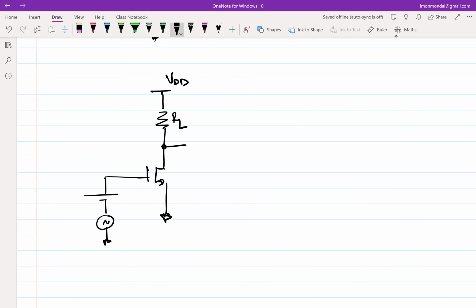And then we saw that if you have RL here, there is only so much gain you can get for a particular voltage supply. Then we said that we will not use RL. We will use a current source, and then try to bias it using negative feedback. And if this is fine, then what will be the gain? GM-RDS, right? So AV in this case will be minus GM times RDS, or GM by GDS.